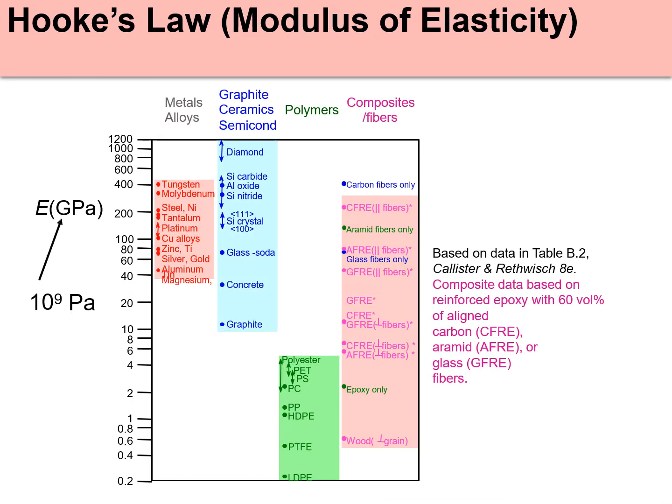Right, so this is a figure which shows the range of the elastic modulus. You can see it shows the modulus for metals, ceramics, polymers, and also composites, for various engineering materials. So in this case, the E for the plastics or the polymers is much smaller or lower than that for the other materials, the metals and the ceramics.